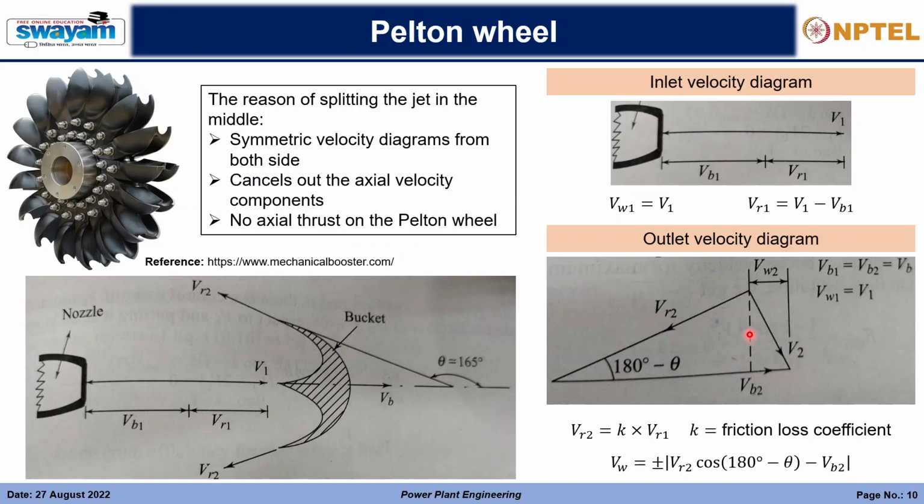So it depends how much the inlet velocity is. Based on that, the absolute velocity will be either like this or in the backward direction like this. That would further impact the calculation of the tangential forces and everything. But for now, let us not consider the sign. Later on we'll be considering the sign, but in this session there are no problems related to that. Now the whirl component. The whirl component is based on the absolute velocity, not the relative velocity. We have also discussed this in the steam turbines.